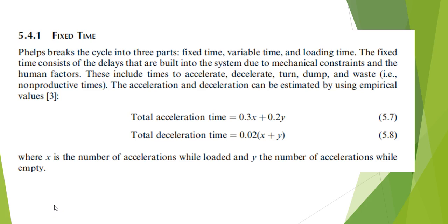There's also another set of theory developed by Phelps that breaks the cycle into 3 parts: fixed time, variable time, and loading time. Okay, the fixed time consists of all the delays that are built into the system due to the mechanical problems and human factors, okay, the truck characteristics and the driver characteristics. So it includes acceleration and deceleration, turning time, dumping, and non-productive times.